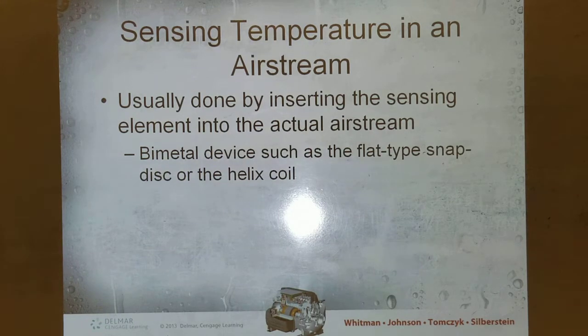So we're talking about airstream, so sensing airstream. The sail switch is just like a sail, and it's inside the ductwork, and as soon as the air comes on, it moves down and closes the switch. So that's basically the best way to detect the airflow.